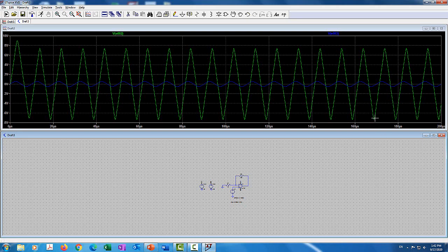And it's a straight line. The reason is that the derivative dV out/dt reached the maximum point, reached the slew rate. From this min to this peak, that's half a period. It goes up in half a period, and then in the second half period it comes down again. So for dV out/dt, the V out is the max range. This is your dV out,